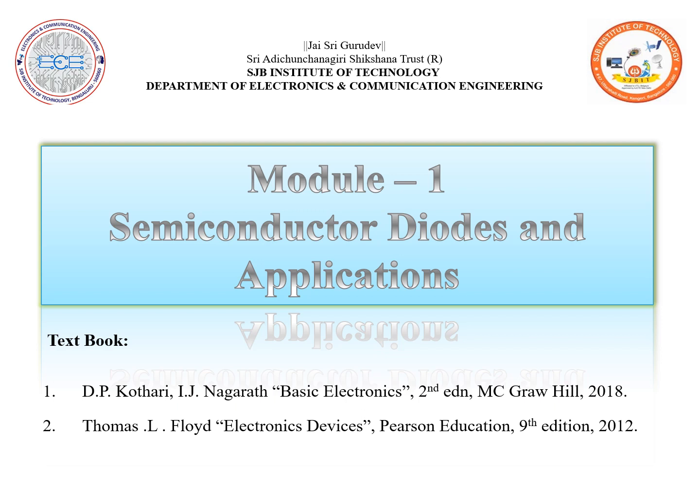Now before going into the capacitor filter circuit, the rectifier is a circuit where we can expect the input to be AC and the output to be DC. But in practice, we cannot expect pure DC. So whatever DC output we are getting, we say it is a pulsating DC rather than a pure DC. Now, in order to convert this into a pure DC, we require some circuit which is going to convert the pulsating DC output from the rectifier into a pure DC.